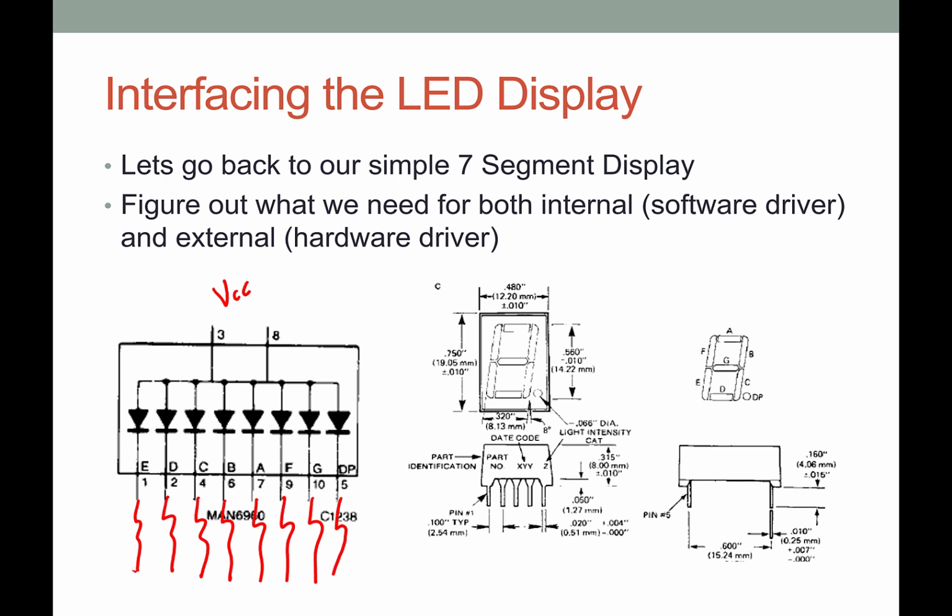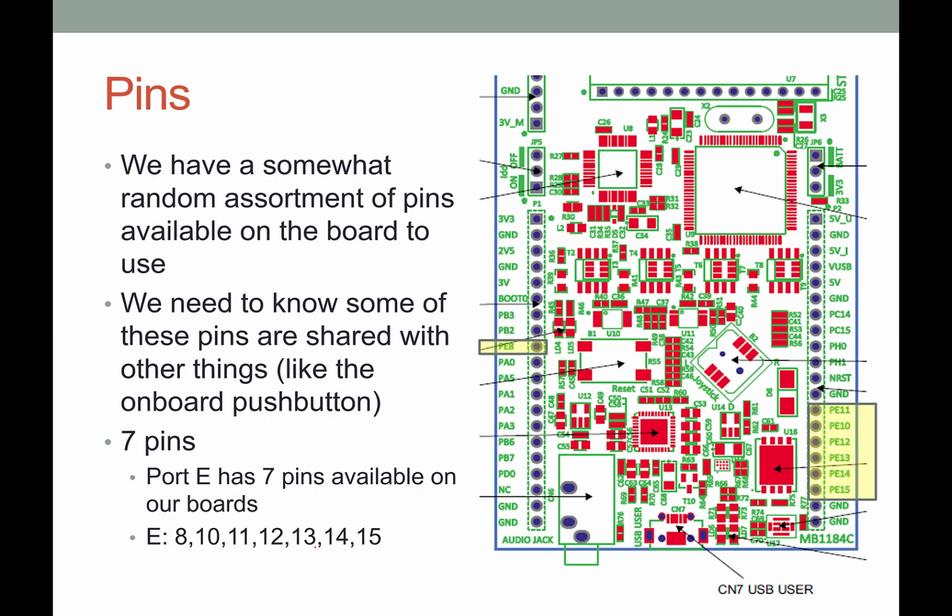And then you can tie that to your output pins, and if your output pins are high, then we're not going to be lit. If our outputs are low, it will be lit. So we're sort of doing that negative active logic by default when we do it this way.